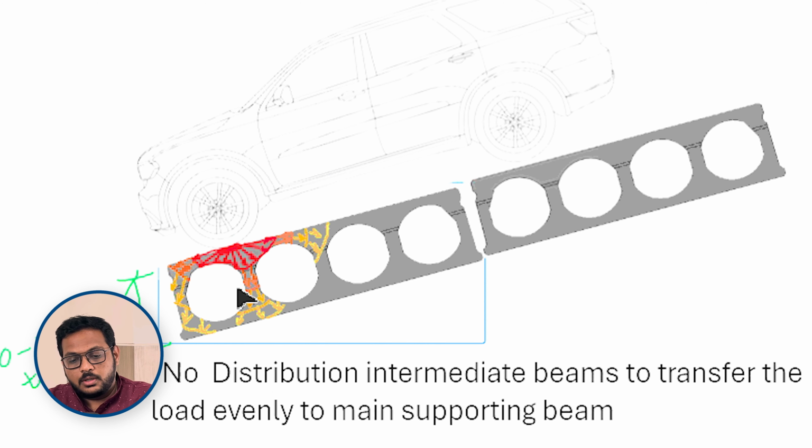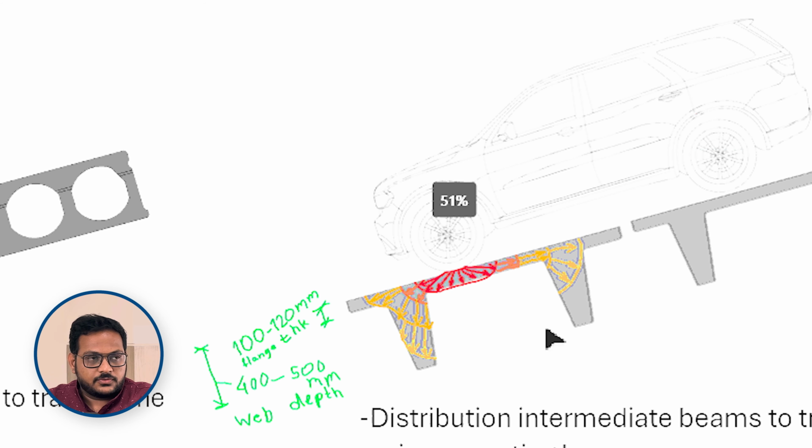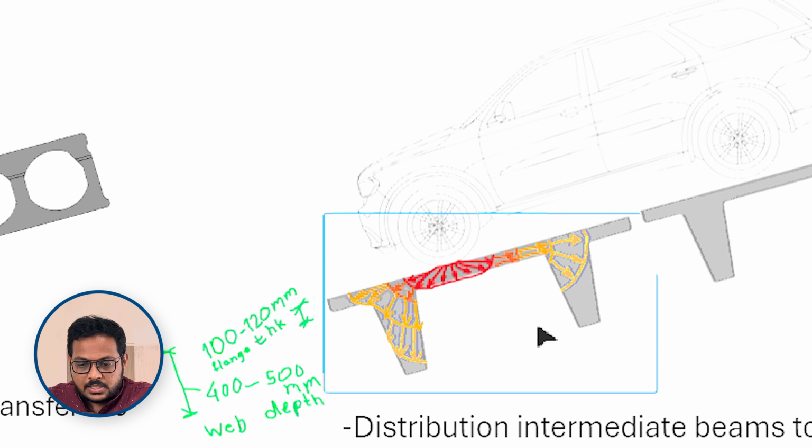But if we go to the T slab, there is a very simple way and a very basic logical thing in structural engineering: force transfers from slab to beam, beam to column. Same thing happens in the T slab. When the force acts on the slab, it directly transfers the load to the beam, which is the web portion of the slab, and this transfers to the column. That is very simple, and there is no disruption. There may be a rectangular hole, but it doesn't matter a lot there because we are giving a certain amount of reinforcement at the top.